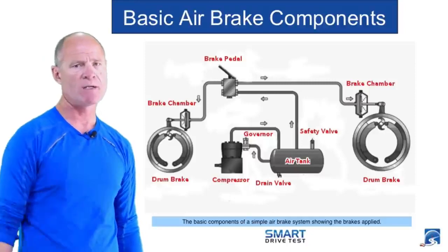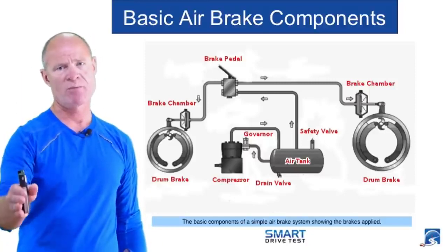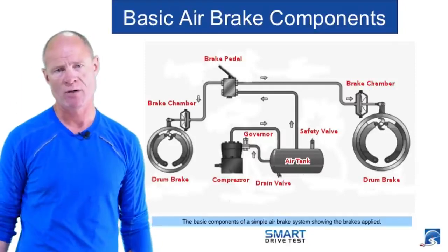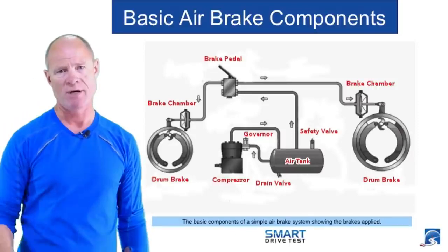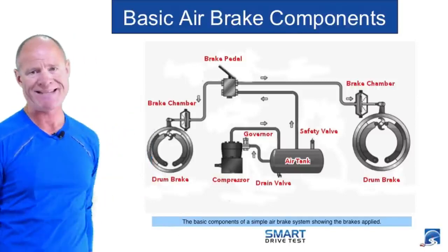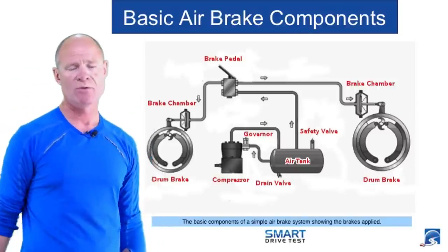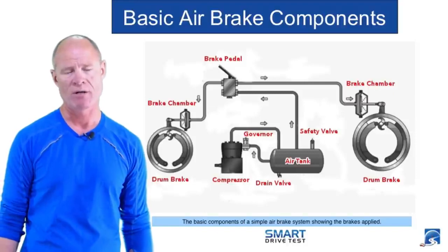That's equipped with air brakes, the service brakes, and the spring brakes. The spring brakes are primarily used for parking and, in the event of an air loss, also for emergency brakes. But for this fundamental system, these are the service brakes, the brakes that you use going up and down the road after you release the parking brakes.